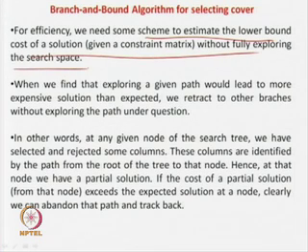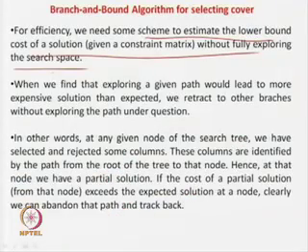That is what the heuristic is. So, what will the heuristic do? A heuristic is a scheme that will estimate the lower bound of a solution, that is, the minimum amount, the minimum number of prime implicants you have to take, without exploring the search space. That is very important. Without actually making the tree, you have to estimate that this is the minimum number of prime implicants required. That means the solution cannot go beyond this.